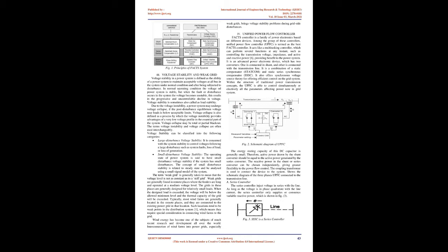In case of abnormal conditions like line loss and generating unit loss, which happen frequently, the UPFC is the most efficient and powerful, and is broadly utilized to manage the power flow through the grid system. Here we use the FACTS type of controller to optimize the power flow in the transmission system. Static analysis is an analysis at the steady state condition, and dynamic analysis is an analysis at the transient condition, such as when faults occur in the transmission system. This chapter describes the basic principle of UPFC and the load flow analyses.